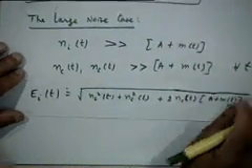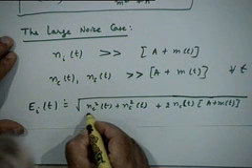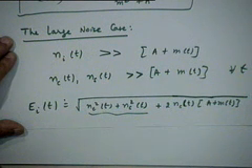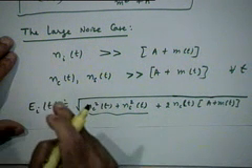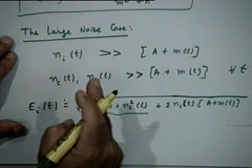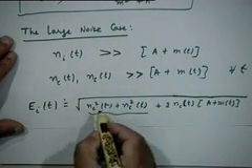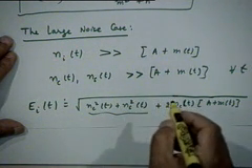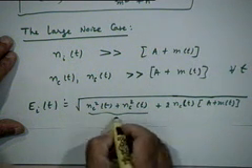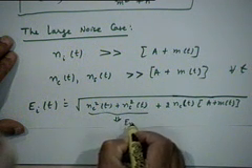If I were to divide this, now just think about it, can I give some interpretation to this quantity? This is the envelope of the noise process itself alone, because noise is Nc(t) cosine omega_c t plus Ns(t) into sine omega_c t. So you can think of this as the envelope of the noise process.